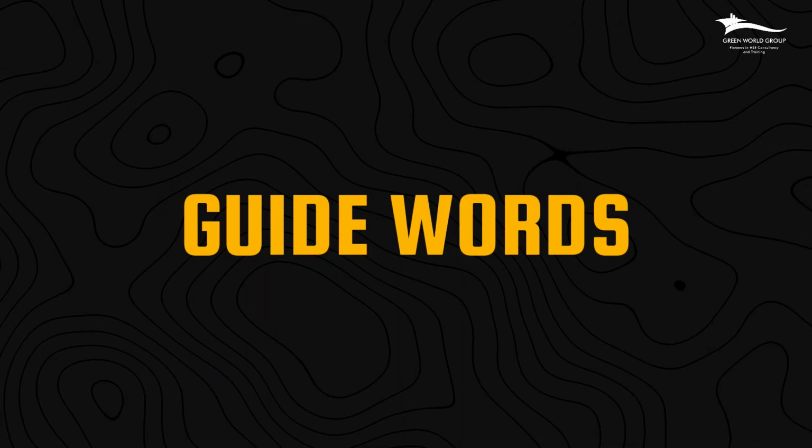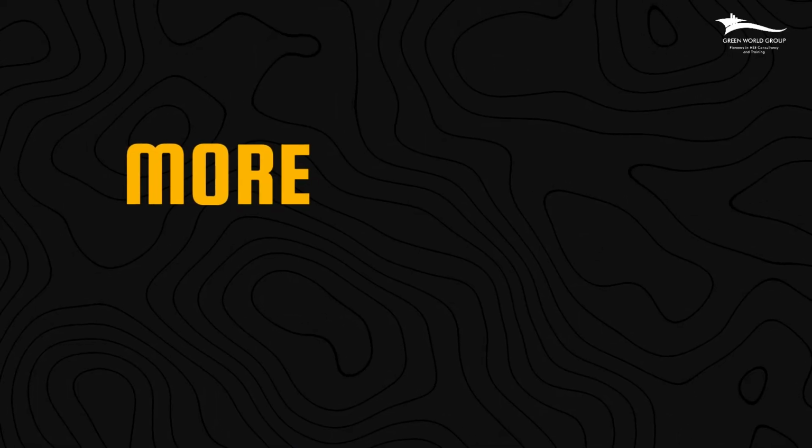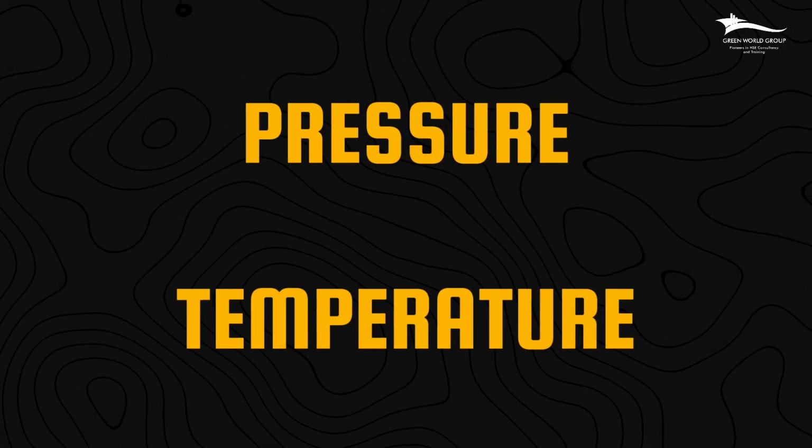Now the third important part is the use of guide words. In a HAZOP study, we apply standard guide words like more, less, no, reverse to specify certain process parameters like pressure, temperature, flow, etc. This will help us identify how the processes may deviate from their design intent. For example, what happens if the flow rate of a particular motor is more, or what happens if it is less. Likewise, that's how we normally do this.